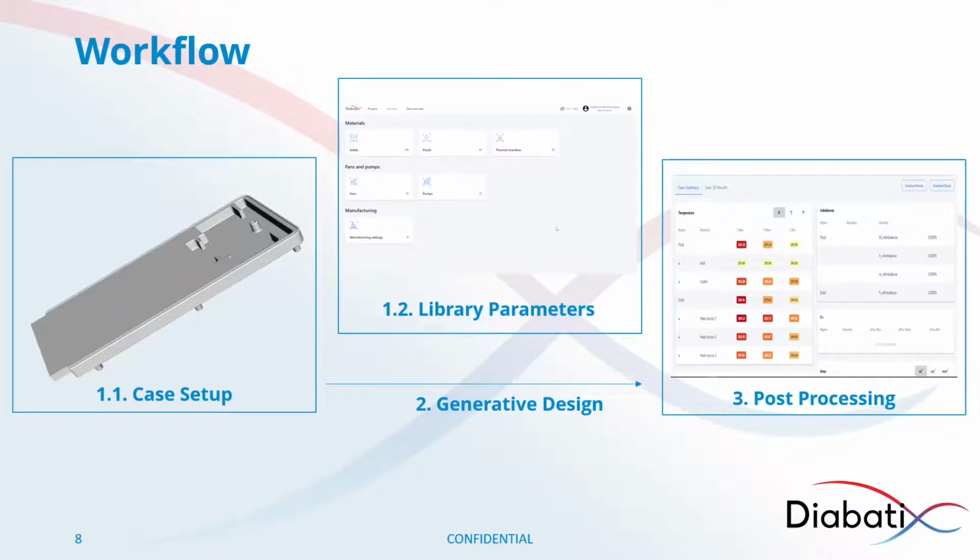On a side note, before I get started on the next thing, I do want to mention that the reason that we have not included a pressure drop constraint in this case setup is simply because it's not necessary. We're using a fan curve as an inlet, and because of that, the fan performance curve kind of takes the pressure drop constraint into account. So we don't have to include that.